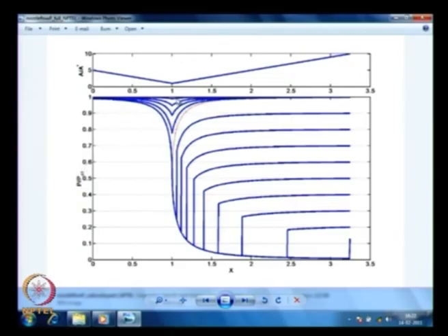Okay. And all the previous curves I showed, they are all here, this region. In fact, I showed you the dotted line also, which corresponds to that 0.9976 number, okay, that is also matching here. After that, you can see what Pb by P naught 1 I used, just directly from here. I used 0.9, 0.8, 0.7, 0.6, 0.5, 0.4, 0.3, 0.2, 0.1. Okay, actually, I used this number slightly above 0.1. I think it was 0.13 or something for this particular nozzle, gamma equal to 1.4 case. Okay, that is the second critical pressure.